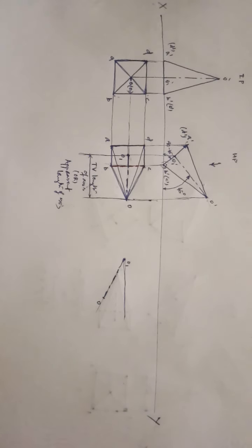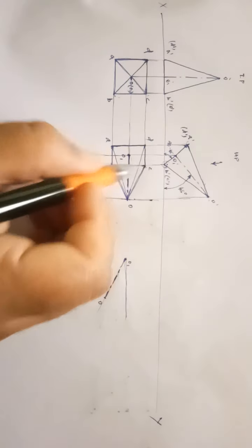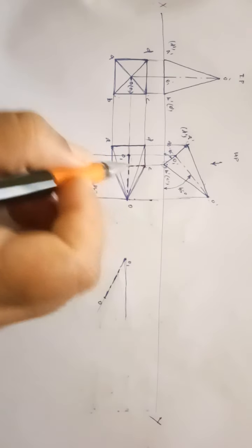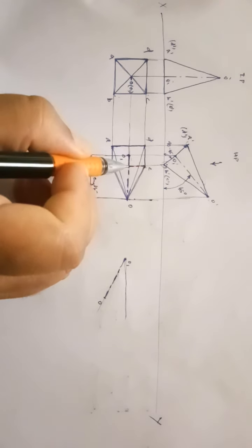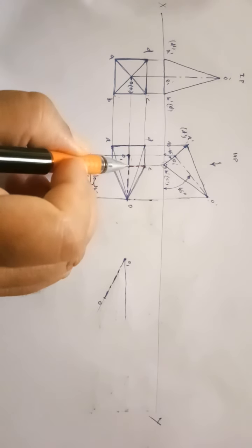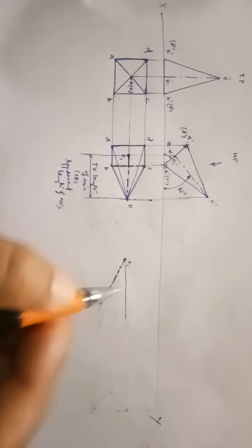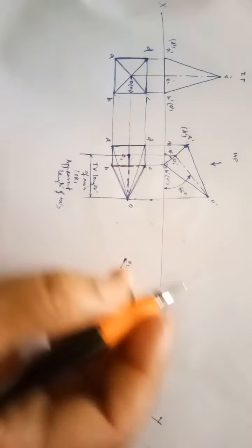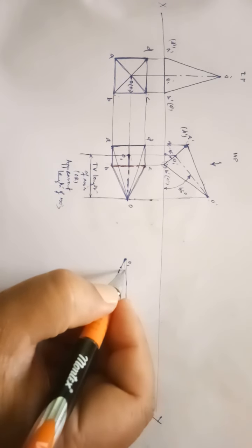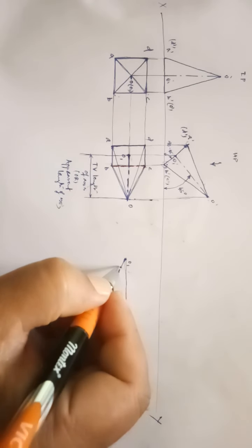Okay, so in this position redraw this figure here. Okay, and first this edge BC, how far it is from O1 towards O is this distance. So measure this distance here. Okay, then draw a line perpendicular to the axis. It must be exactly perpendicular to the axis.